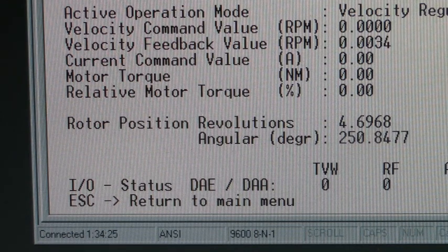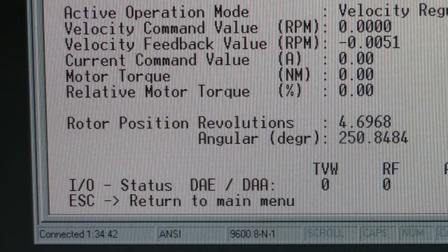So we could apply positive 3 volts to A1, ground to A2, rotate the encoder until we had that timing of 90.5692 degrees. Theoretically. Now, if y'all ever have to change out an encoder, let me know if this works.